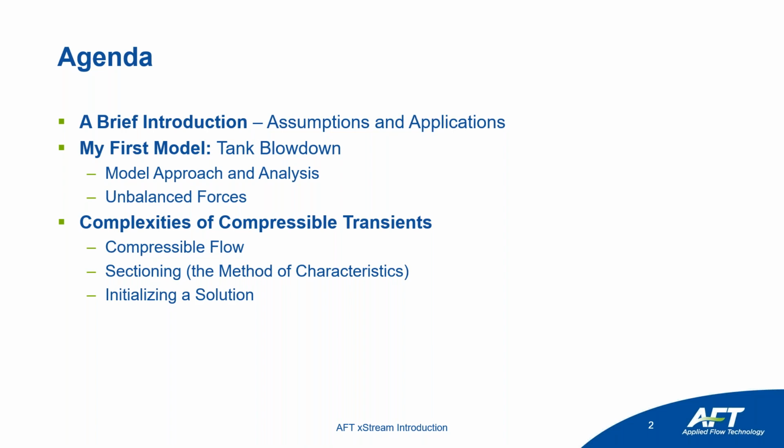So a common theme that we'll talk about is not only do you have to understand the hydraulics of a compressible transient event, it's also important to understand how the solver in the back end works. That way you can create a more staged approach to running your models. You know how to get the most accuracy out of the solver. And also, how do you interpret those results and make sure that they're reasonable, especially as you're making those engineering decisions.